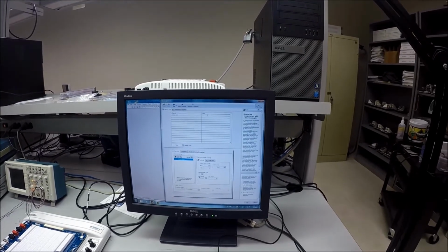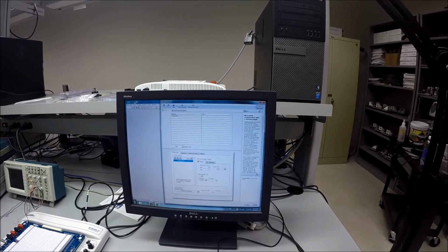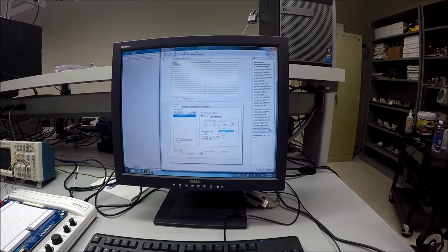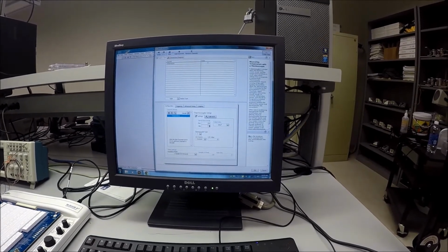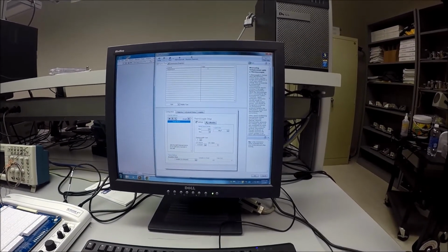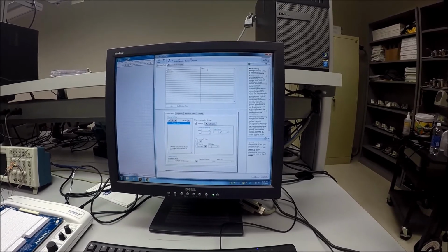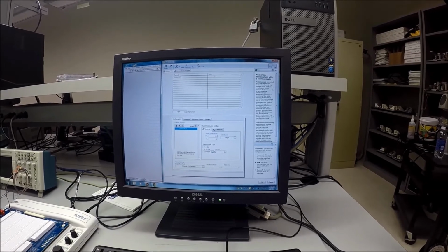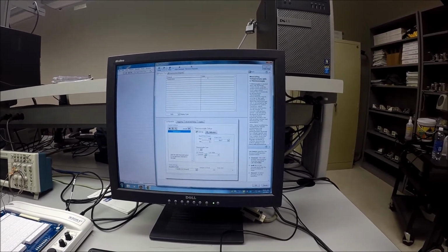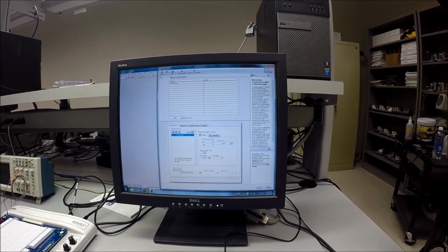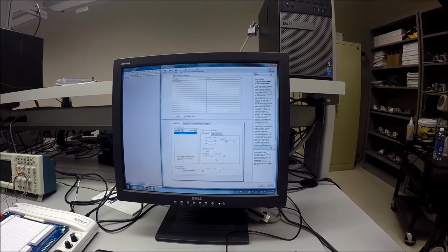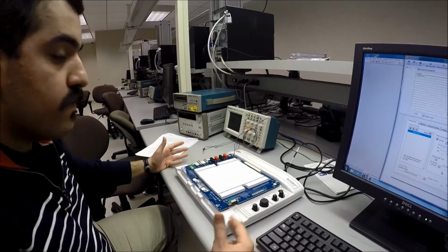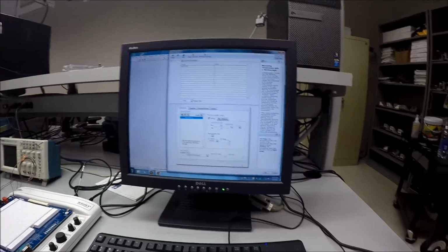Hit the finish button. This is the thermocouple setup. As you can see here, we can set the unit. We want to work with Fahrenheit. Minimum is 32, maximum 150, and since our NI device does not have a built-in CJC, we have to make it a constant. CJC is cold junction compensation, because the thermocouple actually measures the difference between 2 temperatures and 2 voltages.